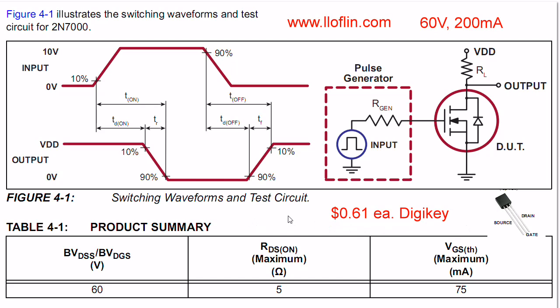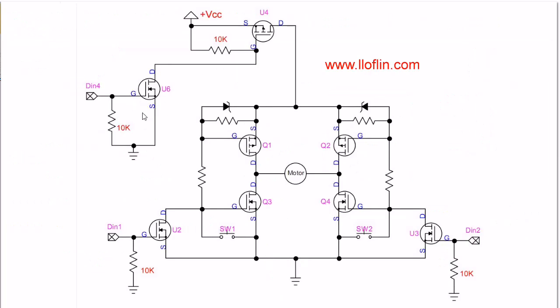To finish this off, there's another thing you have to understand. There is no electrical isolation between the microcontroller and the H-bridge because they have to share a common ground. When you're using optocouplers, you can isolate electrically the H-bridge and the power switch from the microcontroller. But in this configuration, this probably works fine. If you're in a really noisy environment where you're throwing a lot of noise around, you might want that optocoupler isolation.